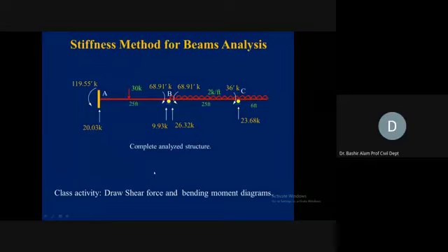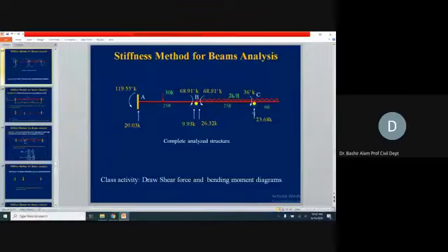And after that, you will have to draw the shear force and bending moment diagram. So with this, we are done now with this one. If I go here, I need to slide this to the left, and this number again we need to move. But anyways, here now we need to show another arrow, and with that we need to show this 6 times 2, which is 12 kip in the upward direction.